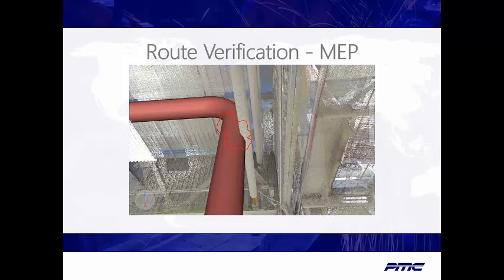This case study is a new weld water line for an automotive plant. The plant layout was in 2D, and the architect designed the new line in 2D. The OEM wasn't convinced of the accuracy against potential clashes due to the density of the MEP in the planned route. PMC's solution was to create a 3D model in Inventor from the 2D drawing and overlay that model into the scan.